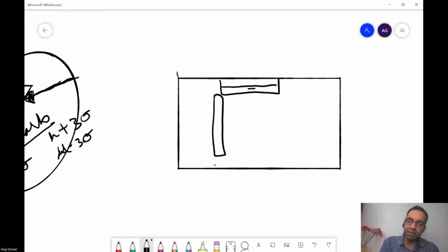Dummy, meaning replica bit line, and we design the inverter at the end of the dummy bit line, buffers there, and this is the enable signal. So we make a circuit which only includes this kind of a path, nothing else. And we measure the delay of this path. And then on this path, we run Monte Carlo.